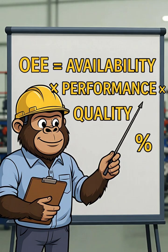Each of these 3 factors is calculated as a percentage. So if your machine was available 90% of the time, ran at 95% of its ideal speed, and produced 98% good quality products, your OEE would be 0.90 times 0.95 times 0.98, which equals about 84%. That's actually pretty good. But notice something important.